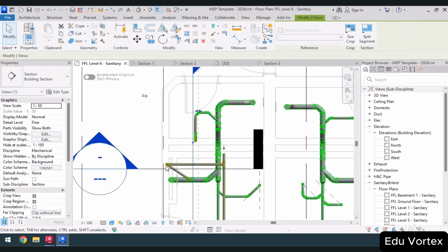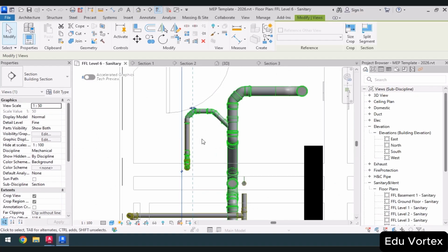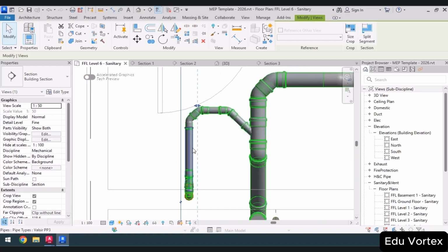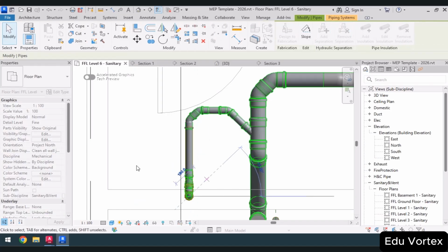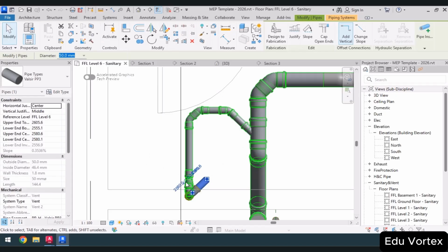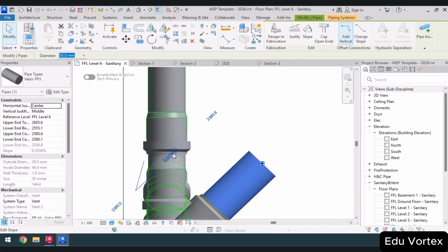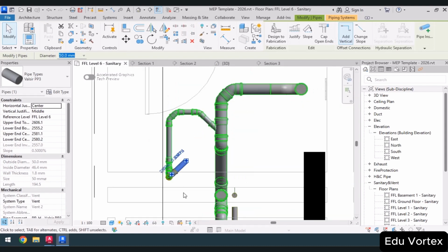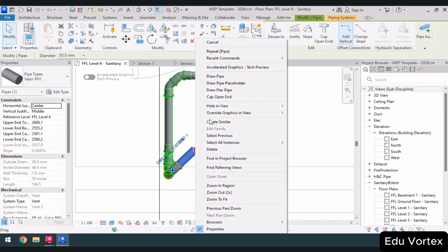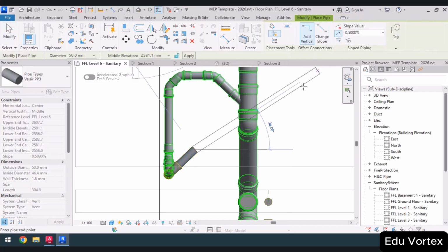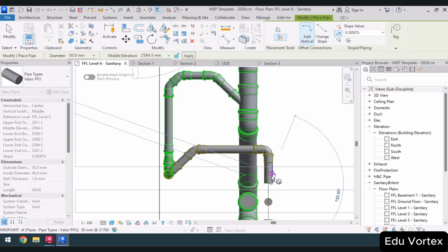It's better to draw the vent here at a 45-degree angle while being mindful of its slope. Notice how the slope decreases. Click on it and enter half a percent, because dragging has reduced that slope. Now I can continue over here and right click pipe shape. It's still directed upwards. I come up to here.